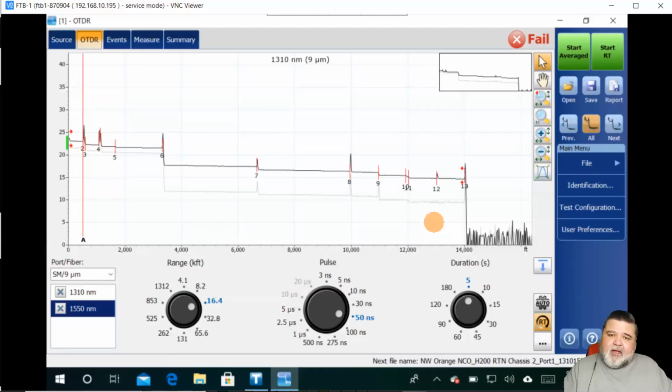We're starting to see a shift with some customers just doing a single wavelength, 1550. When I was testing on the railroad right-of-way, we had very short time to be able to test. And so it was important for us to be able to do it quickly, and we tested only at 1550. And if we had a failed splice, or a failed event at 1550, we'd shoot at 1310 to make sure it wasn't a pinch.